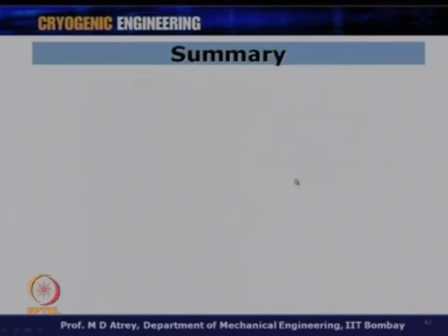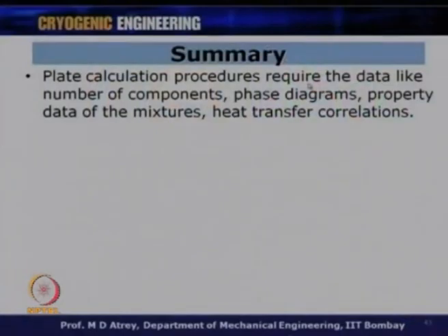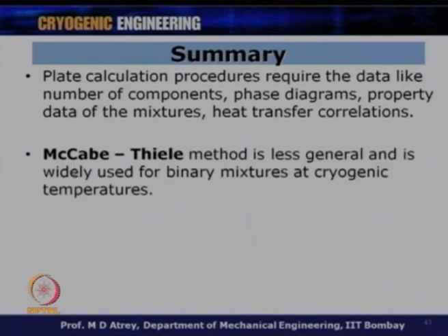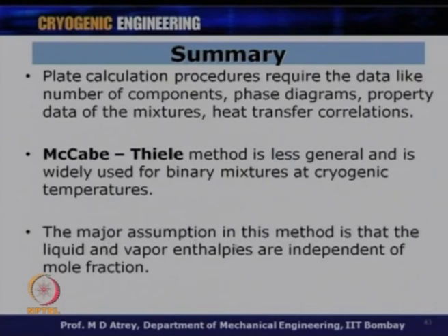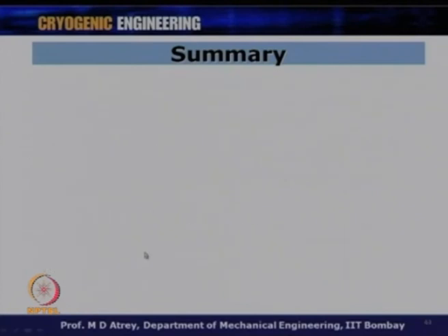So, summarizing what I have just talked about in this lecture, the plate calculation procedures require data like the number of components, phase diagrams, property data, variations of mixtures, heat transfer correlations. The McCabe-Thiele method is less general and is widely used for binary mixtures at cryogenic temperature, and this is what we are going to study in this particular topic. The major assumption in this method is that the liquid and vapor enthalpies are independent of mole fraction, and that is what simplified various calculations.